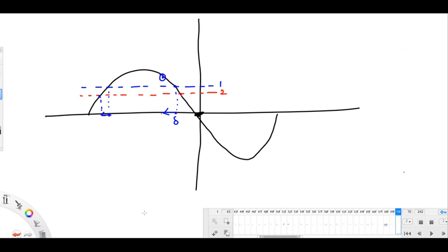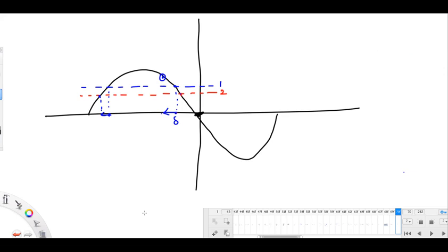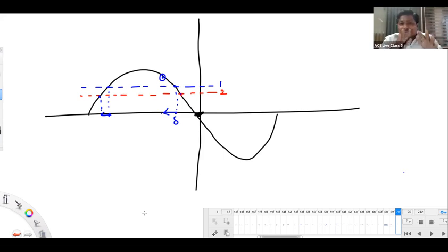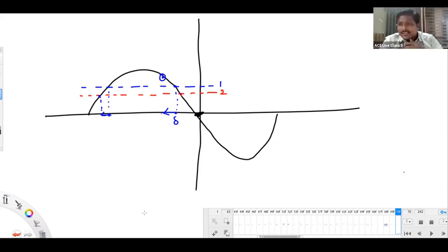Sir, an insulator disc is also a capacitor only, right? First metal link, second metal link, and between them we have a dielectric medium. Between that, leakage current will flow? Not leakage. These are not leakage currents; these are displacement currents or charging currents. Leakage current we neglected. We removed the resistance from our circuit, right?